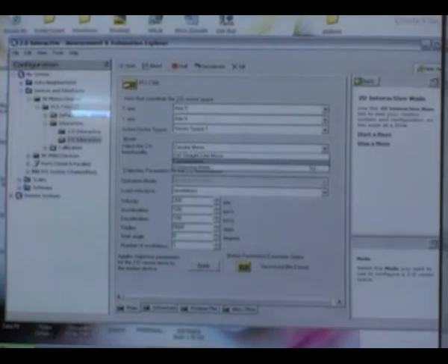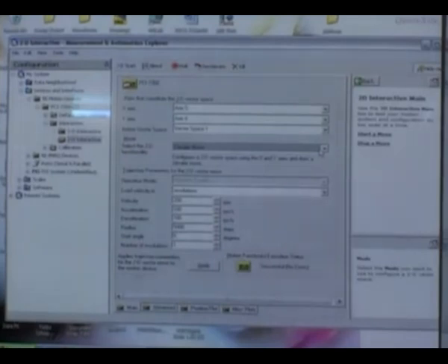So we can go to circular mode, which we have used in our work on making microchannels in the shape of 8. Here axis 5 and 6 are configured in the circular mode. We can change the velocity. We will go to a small velocity. This velocity is in RPM. 1 RPM of the X axis results in 5.55 micrometers per second.